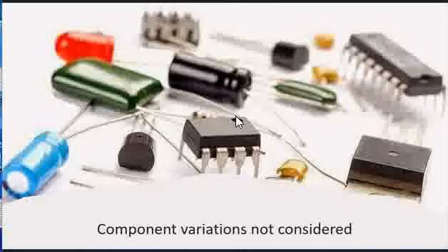And another thing is component variations. This is the ultimate one. When a signal integrity analysis is done, engineers suggest specific terminations as an output of that analysis. They consider that component, perform simulation and see that everything is fine, based on which recommendations are provided.